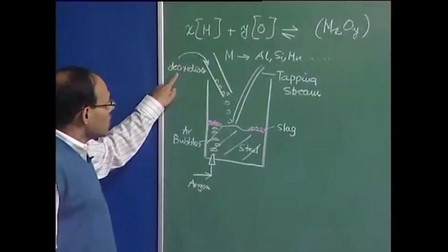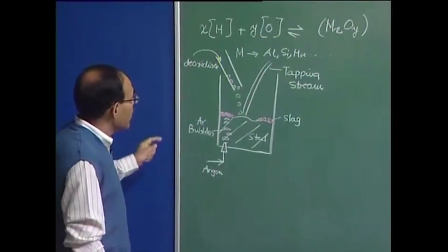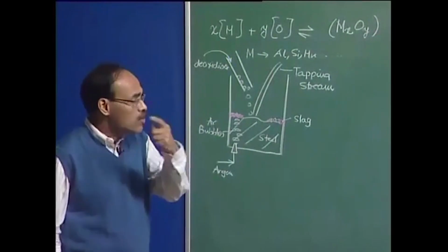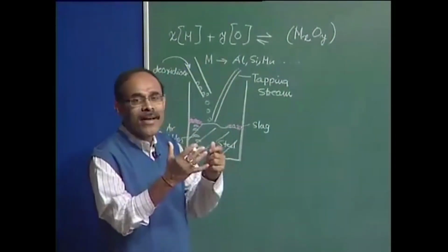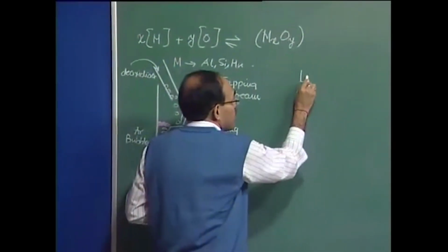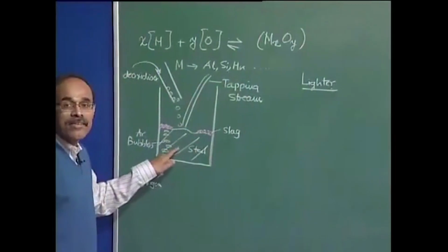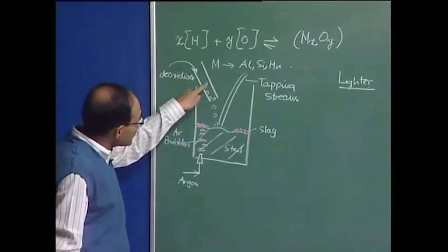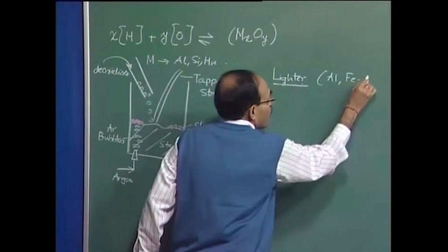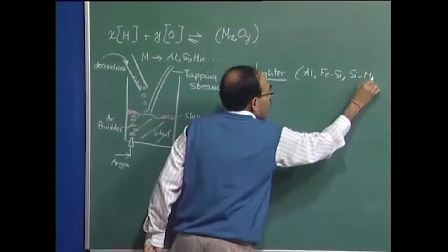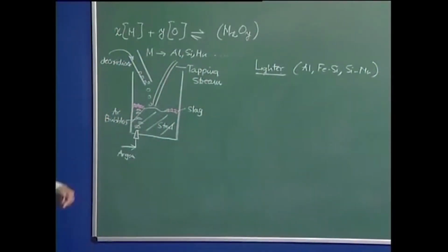Now this shows the bulk addition of the deoxidizer elements like aluminum, as we are talking about. And one property I think you should have been able to register by now is that these deoxidizer elements like ferrosilicon, silicomanganese, aluminum are much lighter than steel. Their density is much lighter than bulk steel. Ferromanganese, depending on the grade, on how much percentage of manganese you have in it,